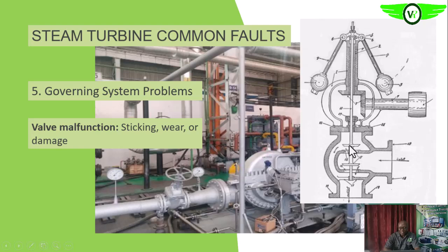Are we getting it? So all these sparkings, there could be wear here that can cause the abnormal leakages of steam. Okay, then this valve could be stuck to a seat, which means that when you require it to lift, it will not be able to lift. And if that happens, it means that no steam will be administered into the turbine. Okay, or it could be stuck halfway.